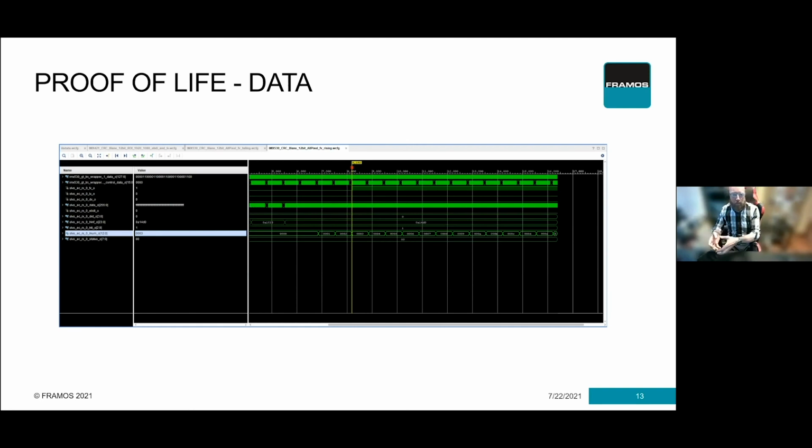You might have the wrong PSRR, that's power supply rejection ratio, i.e., the system can't supply the power at the frequency that you're requesting it, because this column ADC will turn on it. The analog processes will come on and off over time, and then that creates noise.